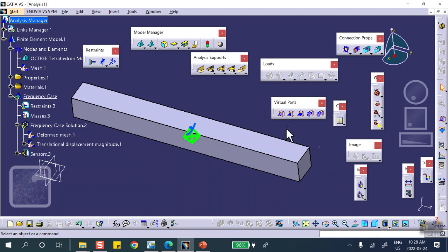You don't care about the frame, you're not designing the frame. You don't care about the wheel, you're not designing the wheel. You are interested in the response of that suspension unit. So you replace everything on this side and everything on that side with a virtual part, which means you don't have to mesh things like that because it's really not a part. But the effect of those, in the form of a force or a restraint, you introduce to the suspension unit. Okay?